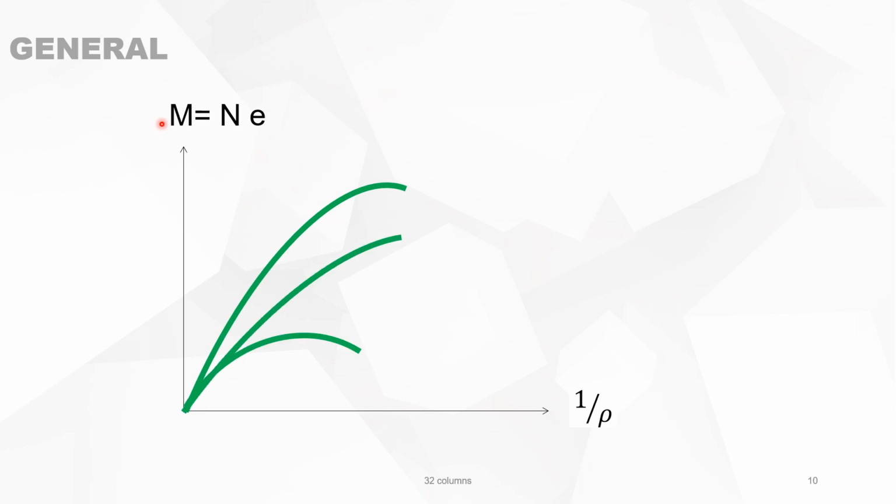We can draw different curves for the internal stability, and doing so you will see that those curves break off at a certain point, and here at this point it's the steel which is not fulfilling its task anymore. So the steel is the cause of the breaking down of the bearing capacity.